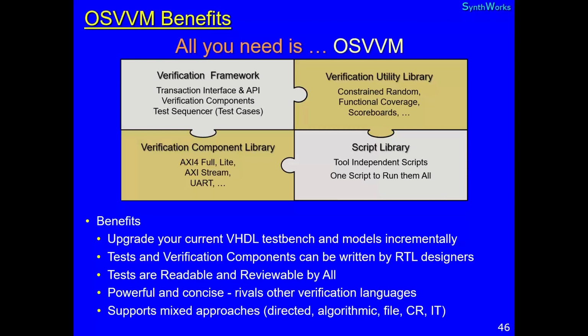We've created an environment that allows verification to be done by either a design or a verification engineer, meaning you can consider your VHDL engineers as non-specialized resources and have them rotate their responsibilities. Tests are reviewable and readable by all. Again, I want to get the software and system engineering team involved. I don't like debugging in the lab. If they tell me, hey, what about this test, and it's something I missed, I'd rather write it in the simulator and test it there than find it in the lab, right?